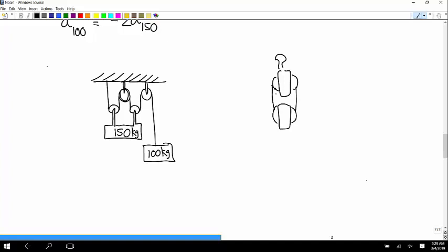You could figure it all out by just taking free body diagrams of the individual things. So in this case, this pulley here is sort of taking half of that weight because the weight is spread out over 4 of these, and it has 2 of them attached here. So whatever you want to see, like how strong it needs to be, just take a free body diagram of that thing. You know what the cable forces are, and go from there.